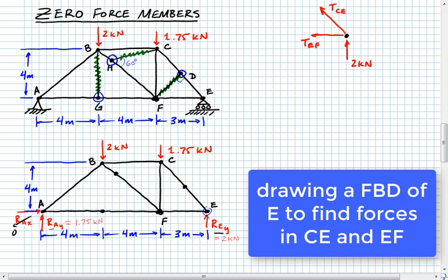To make this free body diagram complete, we're going to put in some coordinate axes. There's X and there's Y. All right, and then finally we need to put in something that we knew about this. We know that it goes over 3 and up 4. That means again that is 5. And from that, it's fairly simple for us to go ahead and do the equilibrium equations off of that free body diagram. We'll sum forces first in the x direction, I guess, where we got rightward positive.